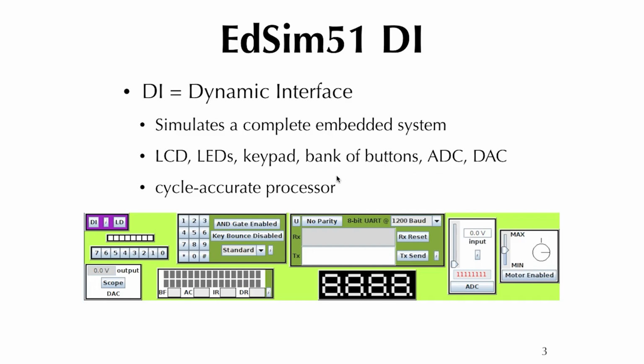Oh, another thing I didn't mention is this is called the UART, or serial port. The reason I didn't mention it was because it's not considered a peripheral, in the sense that it's not an extra chip on the outside. It's part of the processor. In fact, it is really part of the instruction set. So when you want to read the serial port or write the serial port, you actually read or write a register that's associated with the serial port. And then it causes the bits to be shifted in or shifted out. And that's how a little embedded processor can talk to, say, a PC or another embedded processor over a single wire or 2-wire type of interface. So that's a quick overview of its capabilities.